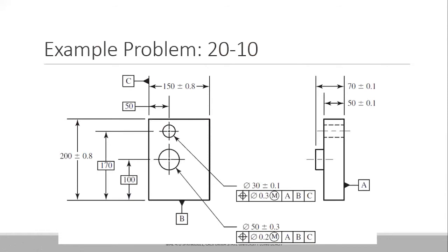So in the absence of any control on the form, you always have to remember that rule number 1 applies. And remember rule number 1, what does it say? It says that it should have a perfect cylindrical form at its MMC. Rule number 1, the envelope principle. So basically it means that at 50.3, at any section of this cylindrical piece, you cannot have a diameter more than 50.3 millimeters. That's what controls the cylindricity.